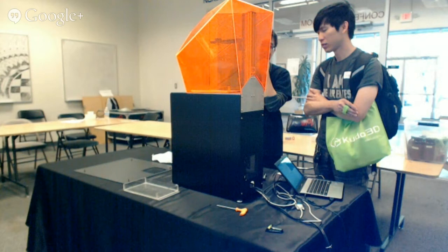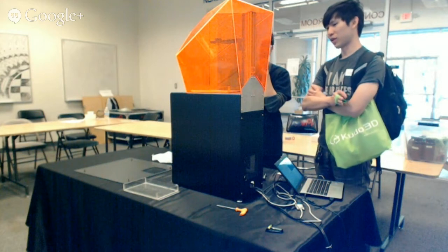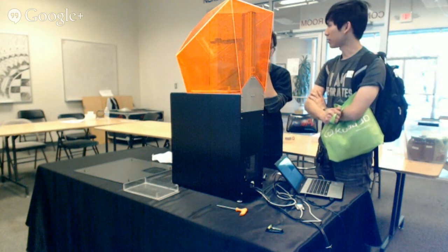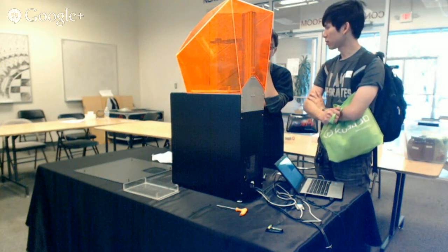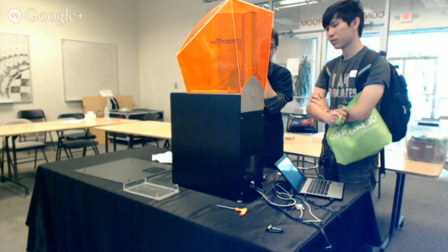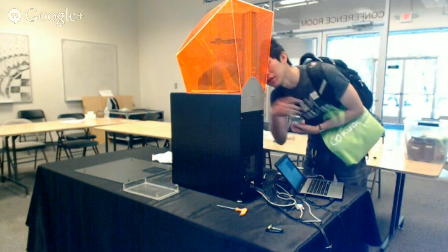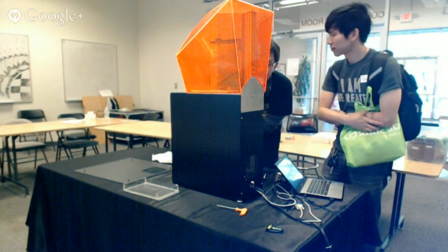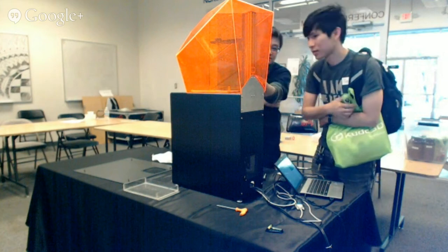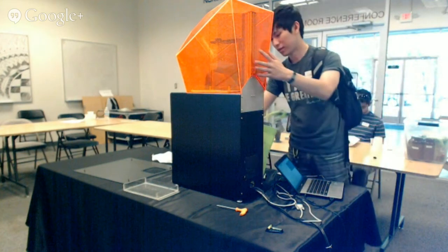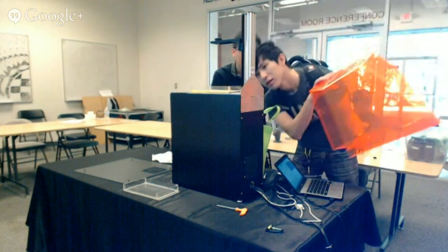Another question: is there any way to make this wireless, the way that essentially you can do Raspberry Pi with an FDM printer and have it put on a multitude of different software? You have to go off the reservation a bit. The software that is documented and drives these printers is Windows-based. So the only way to make this wireless would be to get a cheap Windows tablet, run the control software on that, and use remote desktop or something.